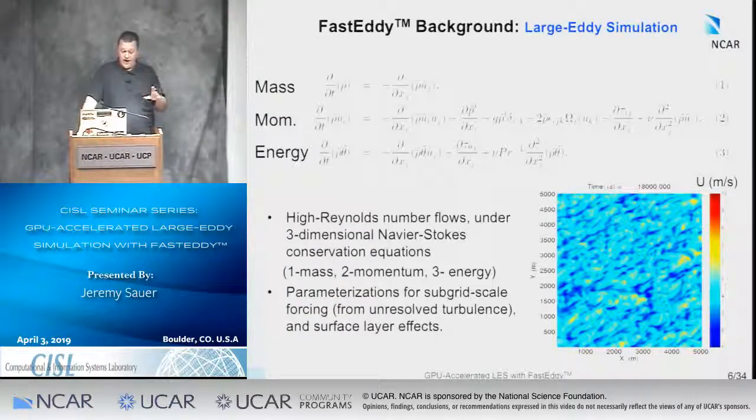We don't do as many parameterizations in Large-Eddy simulation because we're looking to do turbulence resolving scenarios where we model at very fine scales because we want to be in the isotropic range of three-dimensional turbulence. So the only parameterizations we would have in an LES are for subgrid scale forcing from unresolved turbulence and surface layer effects.